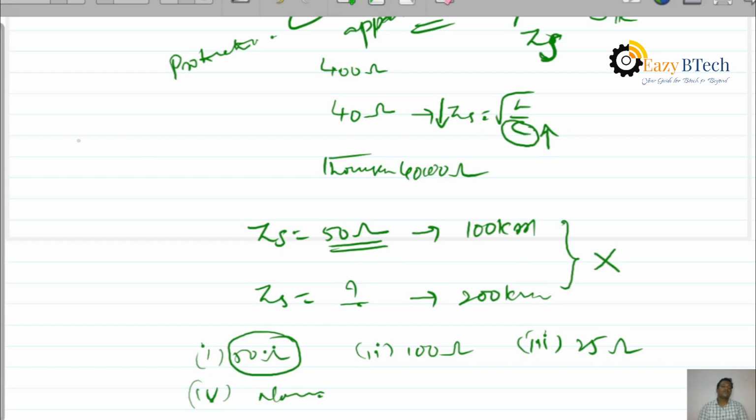Therefore, if we want to protect our devices, we have to design our protecting devices to withstand these voltages. If you know that, less damage occurs. For that purpose, we need to evaluate the surge impedance of overhead transmission systems and underground cables and protective devices. During the surge condition, how much voltage will occur across the line is very important for manufacturing or operating any protecting devices in the overhead transmission system. That's why we need to find out the surge impedance in overhead transmission systems.